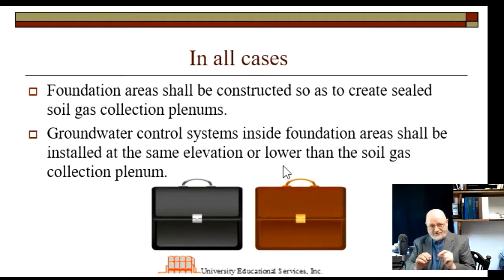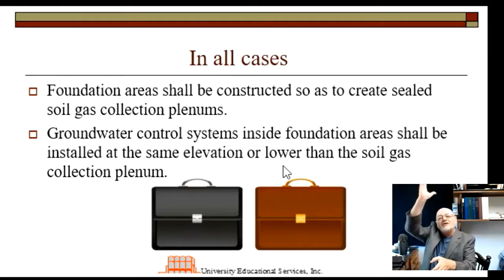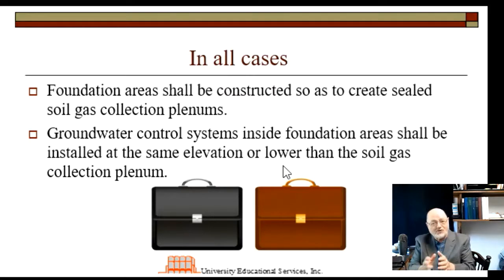In all cases, you shall construct, as it says here, the foundation areas so as to create, as I'm just reading, a sealed soil gas collection plenum. In this first bullet, what we're talking about is, remember, it's soil gas coming up. What we're going to do is capture it before it has a chance to get into the building, and we're going to give it an opportunity to evacuate itself out into the atmosphere before it has a chance to get into the building. And so what's called the plenum here is simply the volume within which we're going to capture this radon and start its trip through its exhaust pipe.